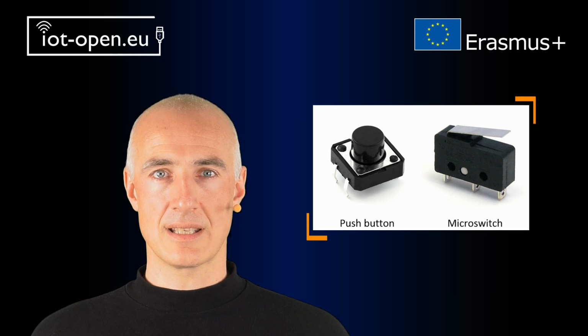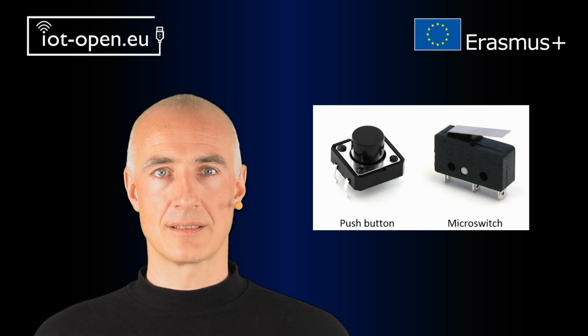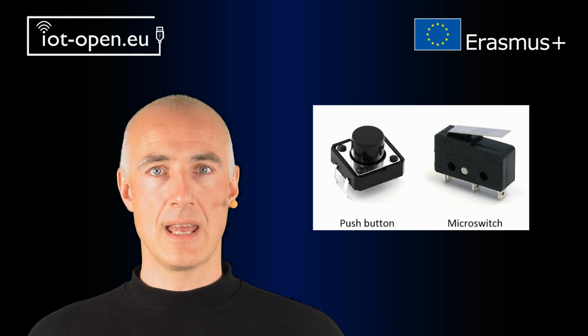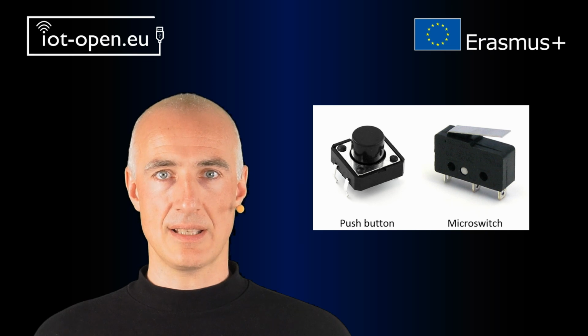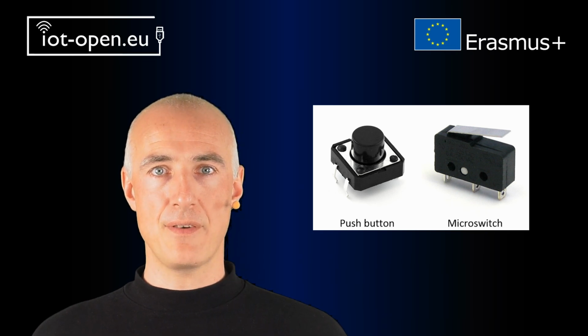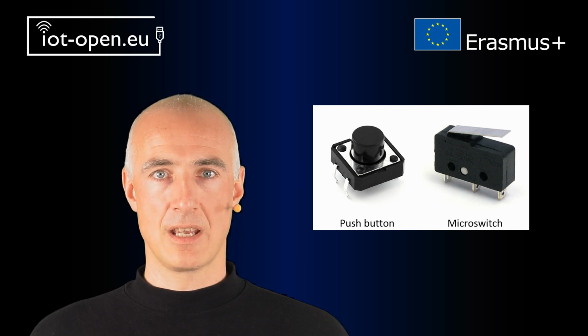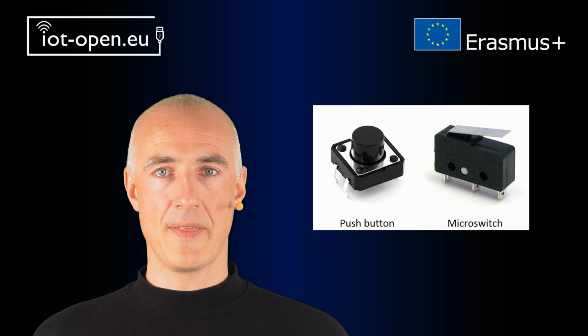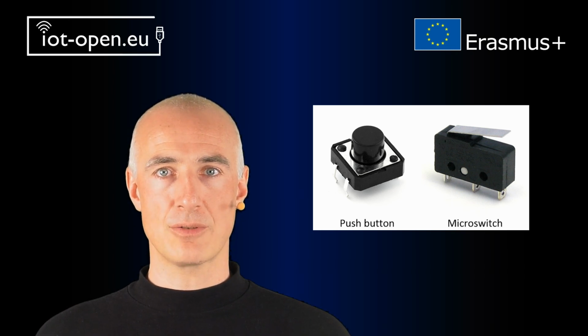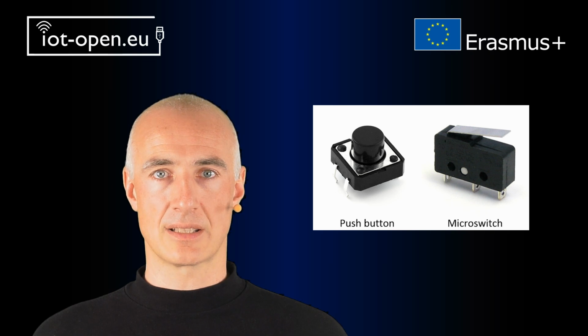A push button is an electromechanical sensor that connects or disconnects two points in a circuit when force is applied. A button outputs a discrete value, either high or low. A microswitch, also called a miniature snap action switch, is an electromechanical sensor that requires very little physical force and uses a tipping point mechanism. A microswitch has 3 pins, 2 of which are connected by default. When pressure is applied, the first connection breaks and one of the pins is connected to the third one.